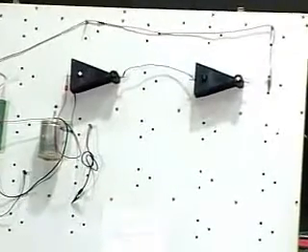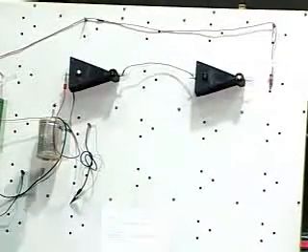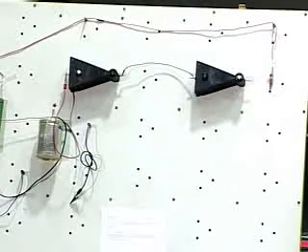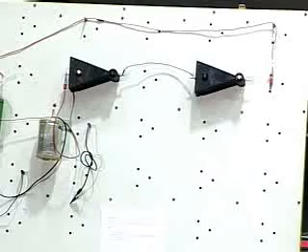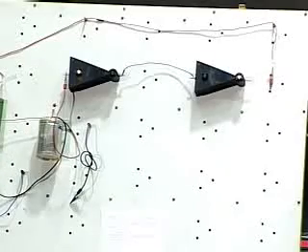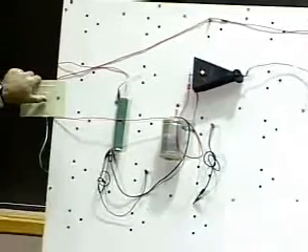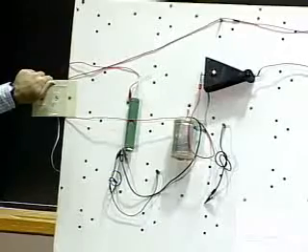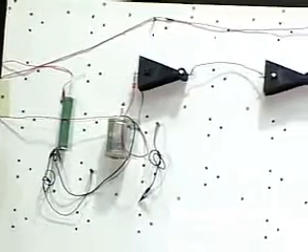Okay, and now I'm going to take the input out. As you can see, it's stored. In fact, we have to wait for a very long time. We don't have enough time to wait for this to discharge. So instead, what I'm going to do now is add also the resistor. Okay? So now I'm going to flip the resistor in parallel with the capacitor to imitate what happens when we have an input resistance. Okay?